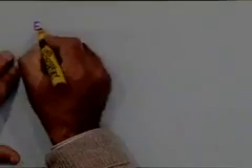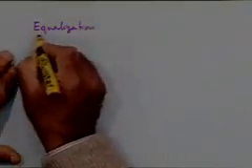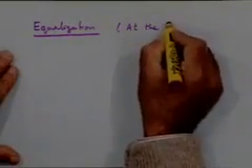One nice thing about linear distortion is that, at least in concept, it is very easy to compensate for it, isn't it? It's obvious. What should we do at the receiver? Put a filter which is a reciprocal of the channel transfer function. So in theory it is possible to remove linear distortion through a process called equalization, right? And that of course will have to be done at the receiver.